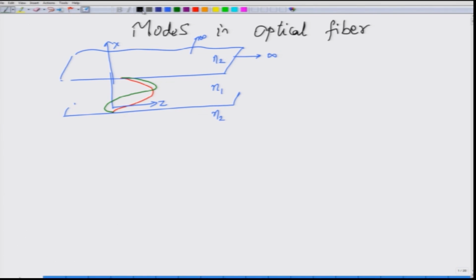So these were the structures that we had seen, and these patterns were associated with TE or TM modes. For a parallel plate waveguide, we called them along with a certain additional index. We said that if n denotes the number of half cycles, then that would be my mode nomenclature. I could equally have chosen the number of minima inside, and that is sometimes done. So if, for example, n denotes the number of minima, then TE0 would correspond to the fundamental mode wherein there is only a maximum at the center and the field never goes to 0.